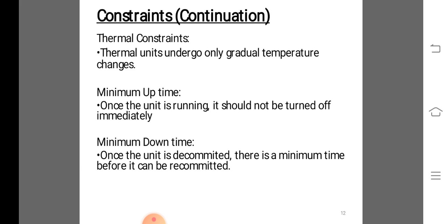The cost for the two can be compared so that, if possible, the best approach, cooling or banking, can be chosen. Up to a certain number of hours, the cost of banking will be less than the cost of cooling. Finally, the capacity limits of thermal units may change frequently due to maintenance or unscheduled outage of various equipment in the plant. This must also be taken into account.